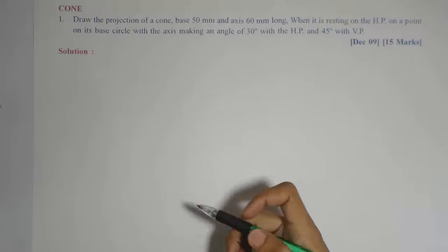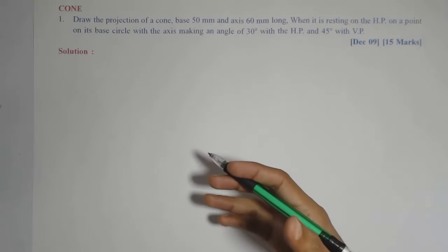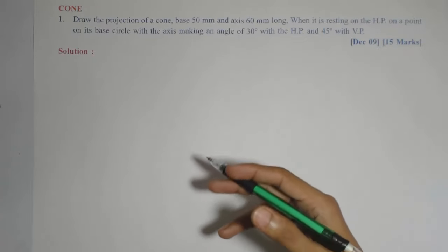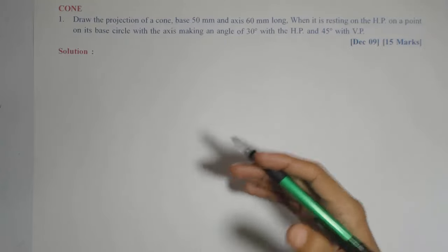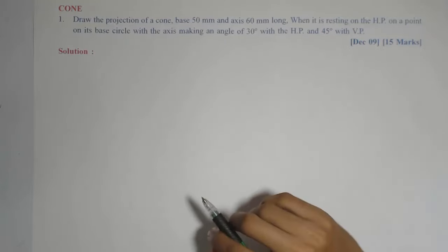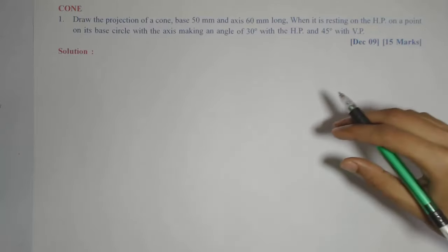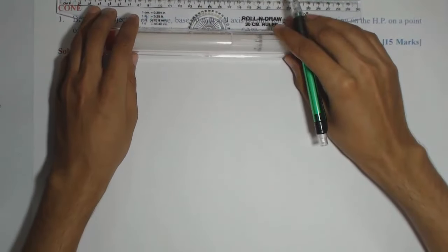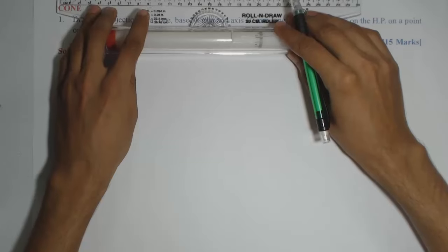Only that much difference. And the circular base will be common. Instead of 2 bases in the case of the cylinder, I'll get only 1 base here for the cone. And for the apparent view, for the circle I'll get an ellipse. So that part will be similar to the cylinder. And here we are also going to get the triangular face in one of the views. So we'll start with the first problem.